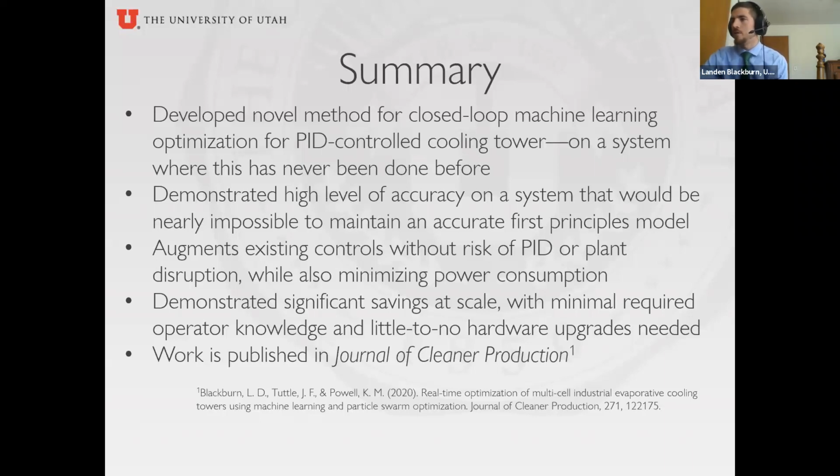We determined there's no risk to the PID stability, which maintains really good control of the tower, and that has priority over minimizing energy. And most significantly, the savings, like I said, are really significant at scale. We have 6.7% less energy over the course of a year on average. And if you look at just the low loads, you get an even higher value. So the more often the tower starts operating at these lower loads, which presumably might happen more often over time, the more savings you end up getting through this.